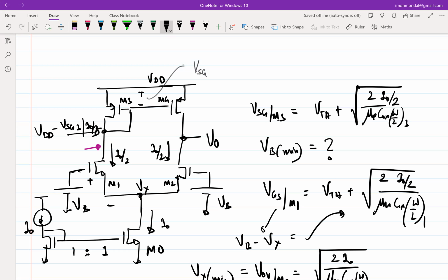You must have used 741 op amps in various experiments. If you keep an op amp in open loop, inevitably it saturates, because you always have some mismatch at the input, and because of the high gain the op amp output tends to saturate. So we should not be surprised, because ultimately we wanted a high gain amplifier. The reason was to put it in negative feedback. That was the overarching reason. We were seeking a differential amplifier which can give us a stable output when put in negative feedback. That is the crucial part.